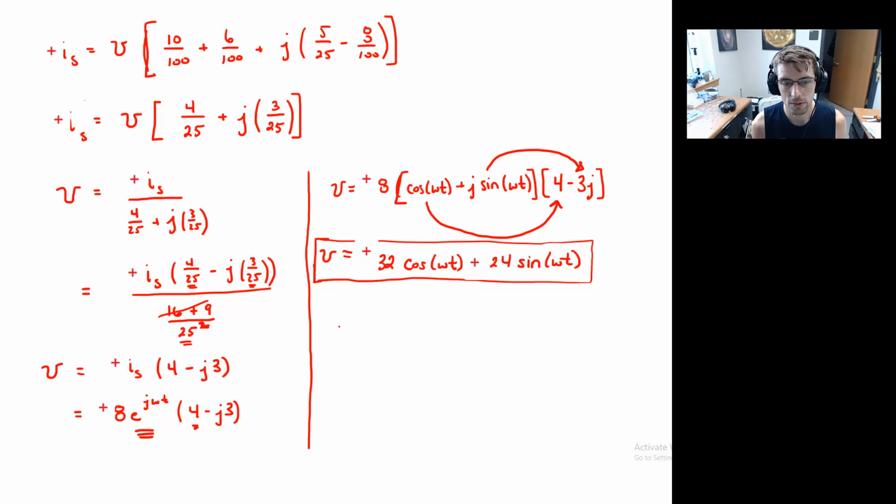Well, we'll say the current through the 10 ohm resistor, what I called R1, that's pretty straightforward. We take V, we divide by R1. Okay. I guess you could say the impedance, right? Technically, I should do V divided by the impedance. I should take this sucker right here and divide by the impedance, Z R1. Okay.